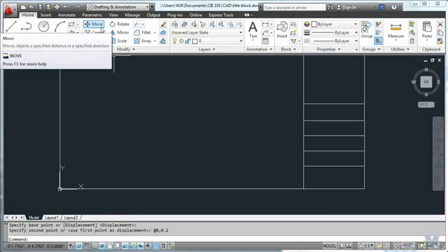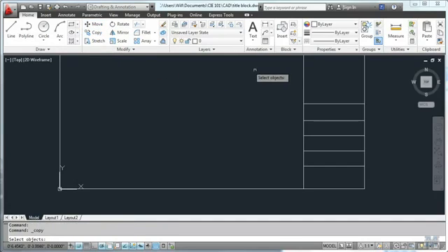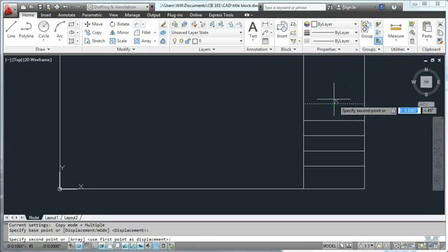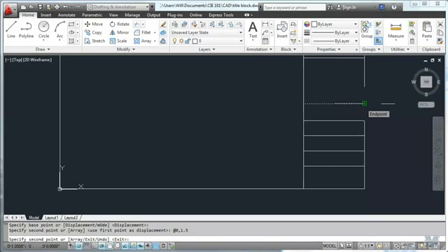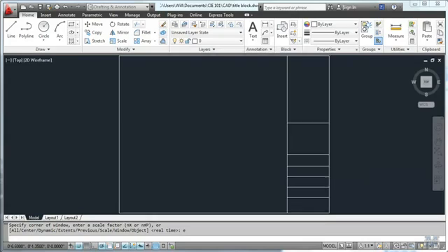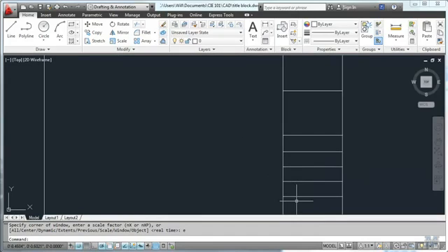Now let's use the copy tool. I'm going to make one more box here. We're going to copy that line from that point. I'm going to go up 1.5 inches, so 0,1.5. Did I type it right this time? Yep, looks like it. Hit enter. And I think that'll give us a pretty good layout here. Zoom extents. So that's good so far. All right.